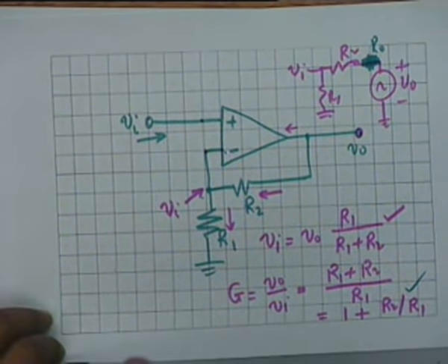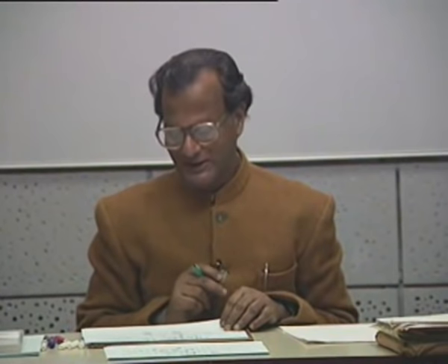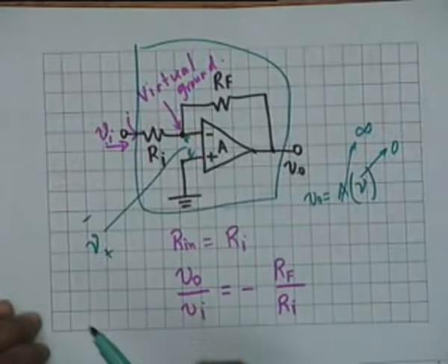Why do we do this? We connect resistance in this case and not in that. We want a non-inverting gain, then this is the configuration. We want an inverting gain, then the previous circuit that we drew, this is the configuration. Why do we do that? We want to get a certain gain, and so we determine the gain through two external resistors, RF and RI.